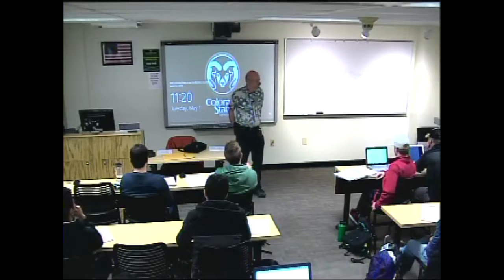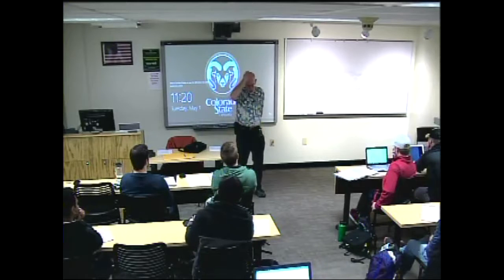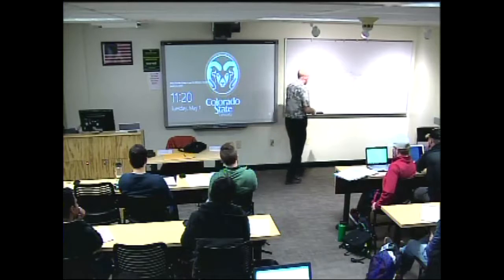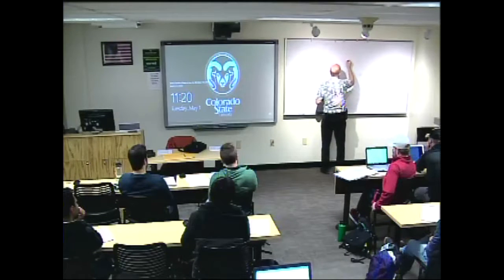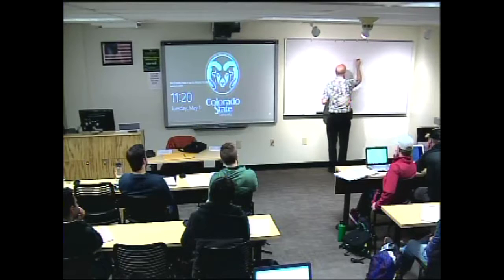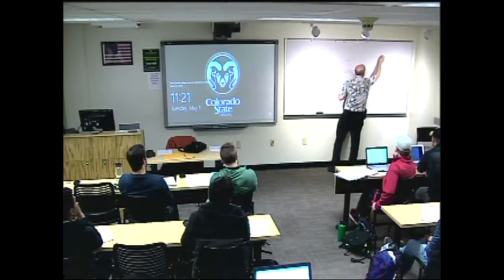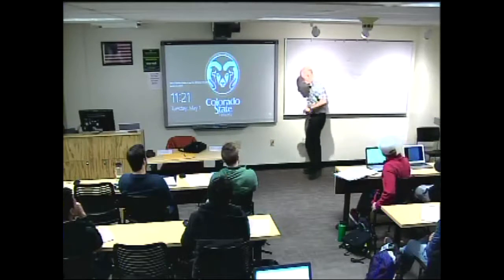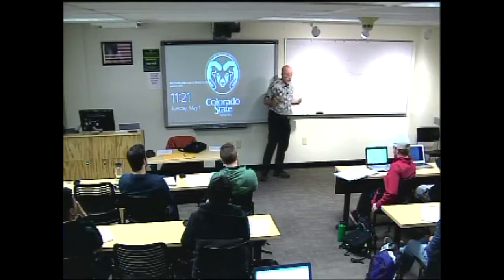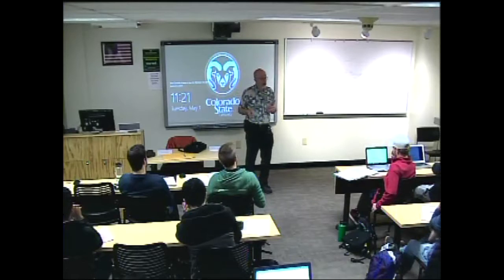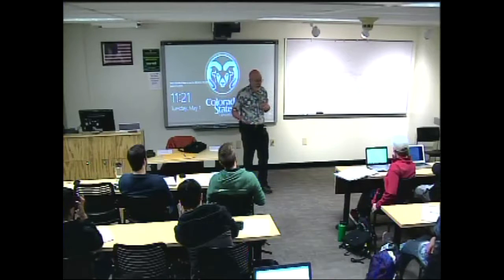Right. And perhaps just because of my training and thinking about photodetectors, I usually think of photodetectors as a source of current as opposed to a source of voltage. And so remember our formula for shot noise is that it's equal to 2 times the fundamental charge times the average current times the effective bandwidth. And so if I change the concentration of molecules for the same level of pump excitation, I'm changing the amount of fluorescence signal coming off, the power of fluorescence.